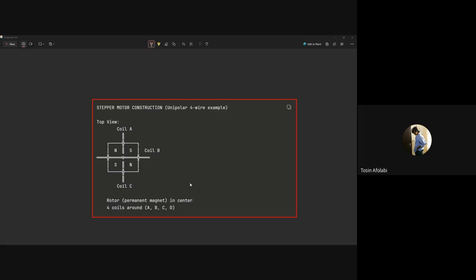Now, the last but not the least type of stepping is micro stepping. What this is, you subdivide each step into smaller increments. That's 1/16 micro stepping. So that's going to be 3200 steps per revolution. So this is ultra smooth, like maximum smooth. It's like when you're watching a movie in 4K at 320 FPS. So that's the way it is.